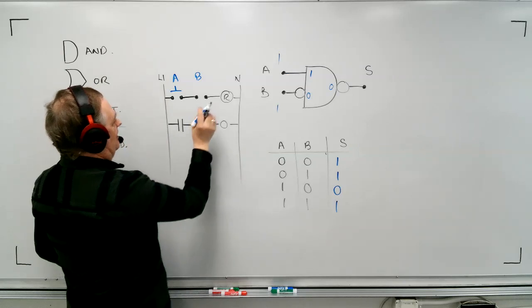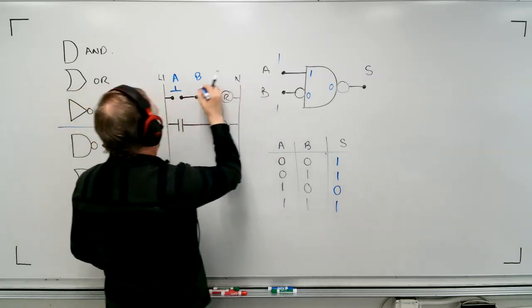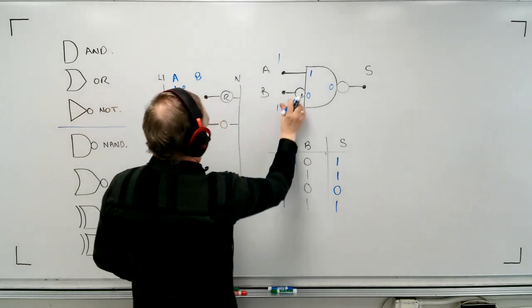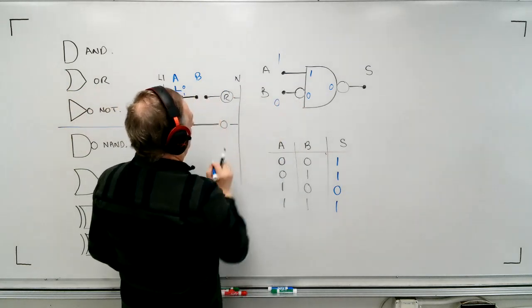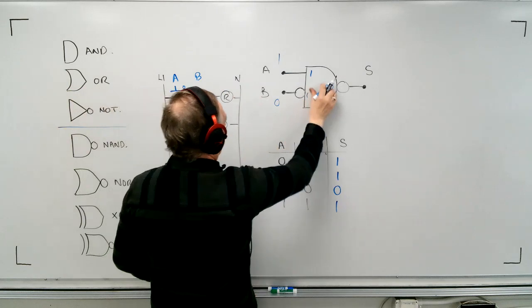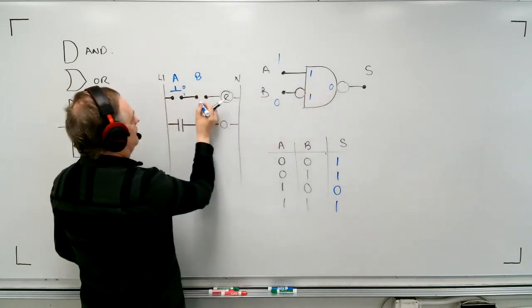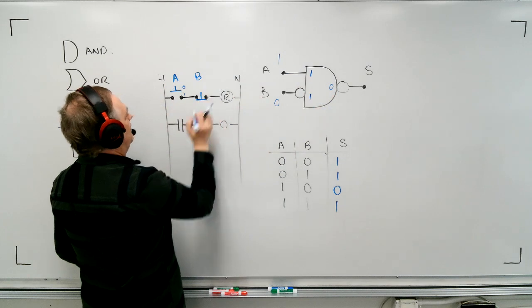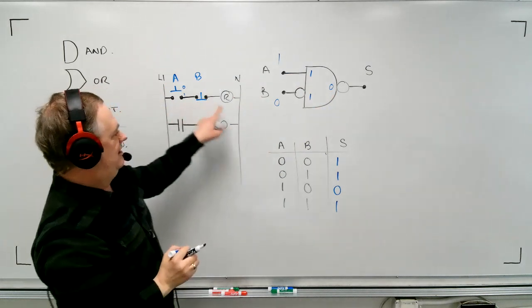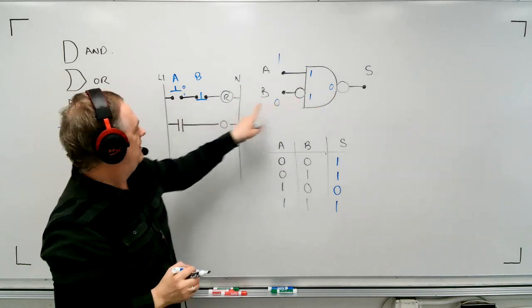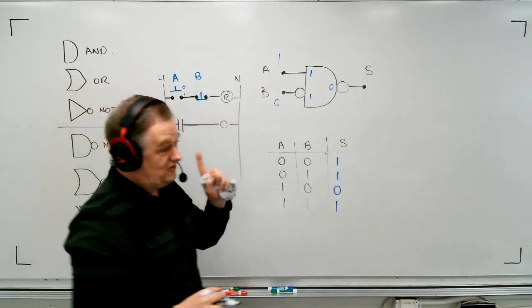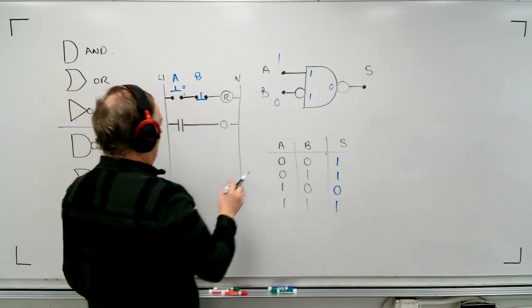B is actually the opposite. So think of it this way. It's because this is 0 and this is 1, right? If B is 0, what actually happens in here? Well, that becomes a 1, right? So we do this when we're drawing this. We make this a normally closed button. If there's an invert on the input, we use a normally closed button to represent this. And you're going to see operation-wise why it works, how it works like that.